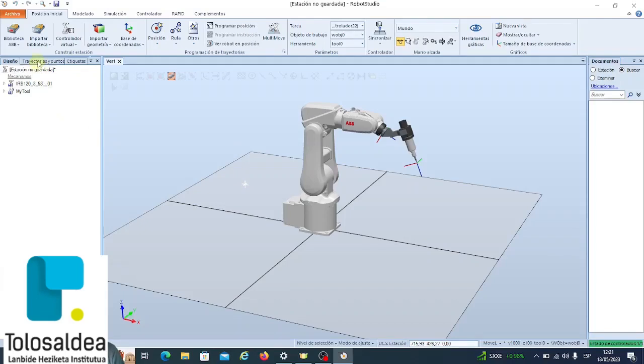At the top left, in the tab Paths and Targets, we will see that we already have the controller. Within Work Objects, we will have a Work Object. By means of this we can program points and positions of different elements. To give the robot different poses, we can do it manually. To do this, click on the Freehand tab, under the Reorientation Movement option.